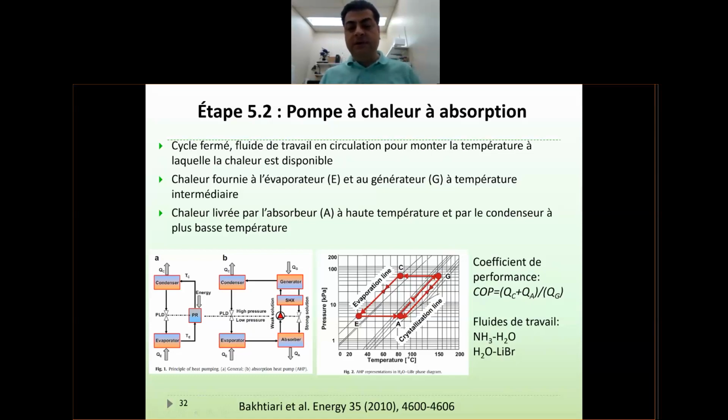This is just one example that shows how pressure and temperature look. Let's start from the E, the evaporator. You see here the temperature, for example, could be 30 Celsius, just as an example. So here the volatile part goes to absorption. In the absorption, you see the pressure is the same. So evaporator and absorption operate at the same pressure. Okay. So after absorption, you have a pump. So you are pressurizing the binary working fluid to the generator.